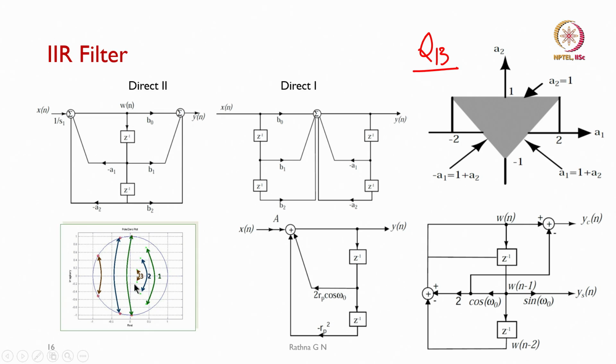So, this has been worked out over the years, and we know that in IIR filter we will be designing our filter using the analog domain, and we will be doing the transformation. So, we know that most of them are Butterworth filter that we will use, or Chebyshev 1 and then 2, and then the elliptic filter that we can design in the analog domain.